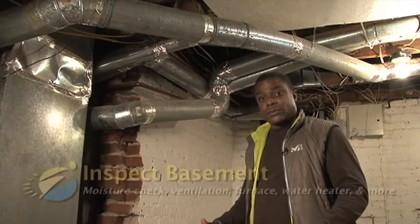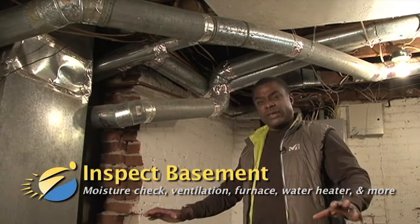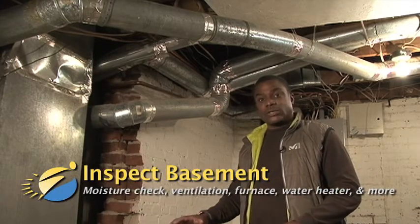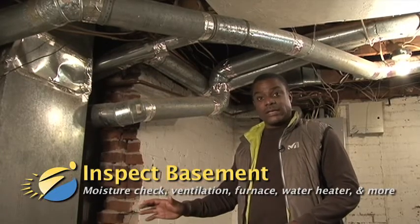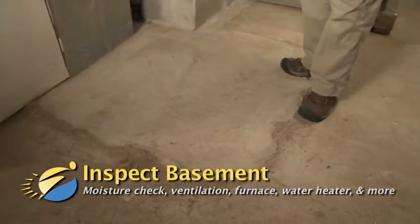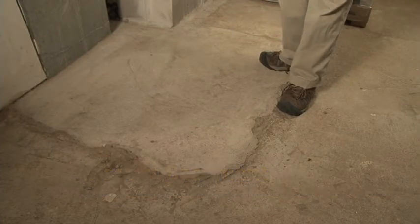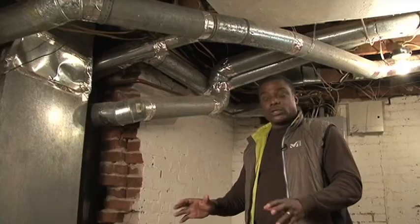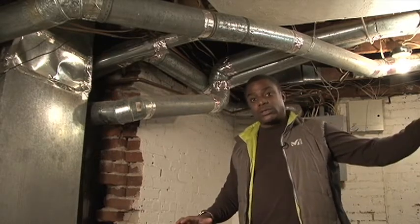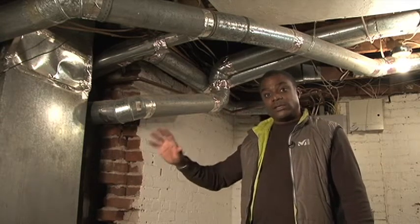As we come down into the basement, there are a few things that we're going to want to be looking for. We want to look on the floor and see if we see any evidence of water, standing water, or water that has been there. That would be an indication that there could be some drainage issues or a leak going on. We don't see any evidence of standing water or water damage, discoloration. So really, this floor looks good. We also want to take a look at wall insulation for the basement, as well as rim joist insulation in the basement. And then we want to take a look at the furnace and the water heater and the associated ductwork.